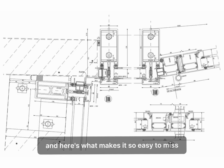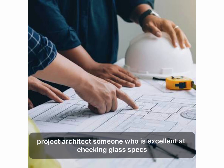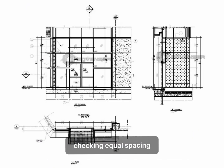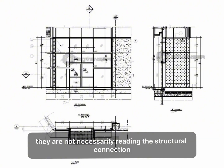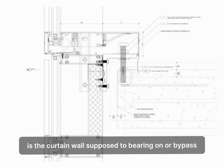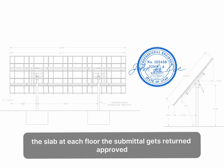And here's what makes it so easy to miss. The person reviewing that submittal is usually the architect's project architect, someone who is excellent at checking glass specs, checking equal spacing, checking symmetry on elevations, and verifying finish colors. They are not necessarily reading the structural connection detail and asking, wait, is the curtain wall supposed to bear on or bypass the slab at each floor? The submittal gets returned approved.